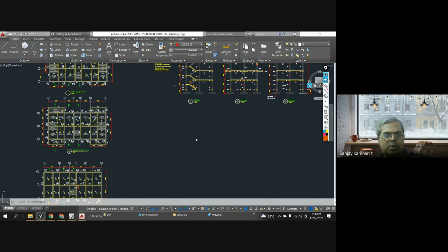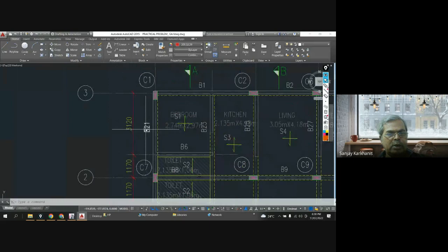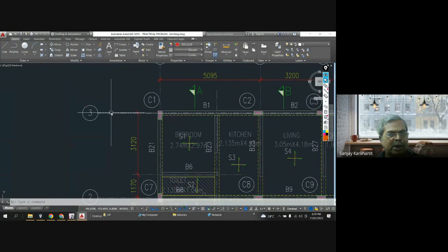Okay. Hello. Are you getting it? So here you are saying, see what is the grid line? You have drawn a grid line over here. So ETABS will draw a column something like this, and it will draw a beam something like this, and not like this. Okay. See, this is your physical condition and this is your mathematical condition.